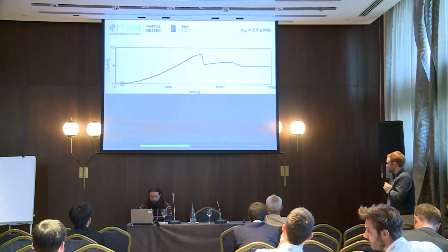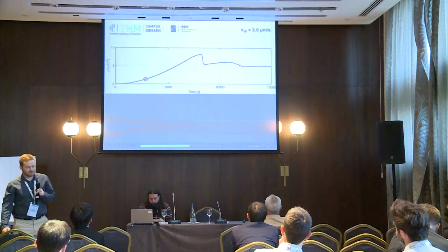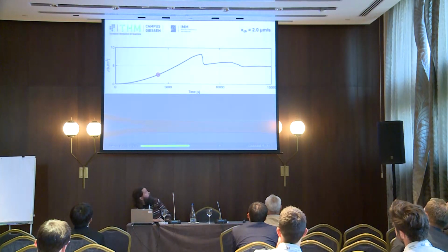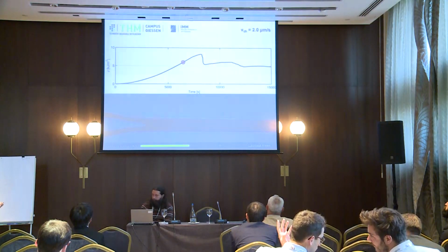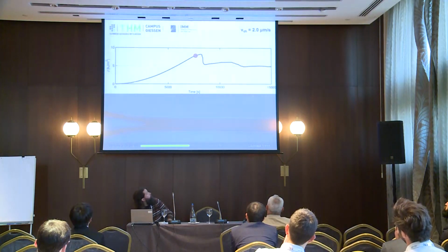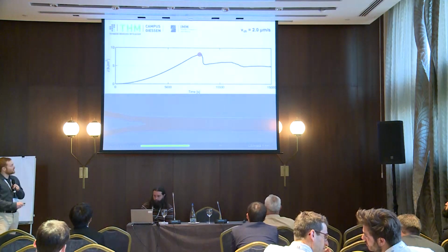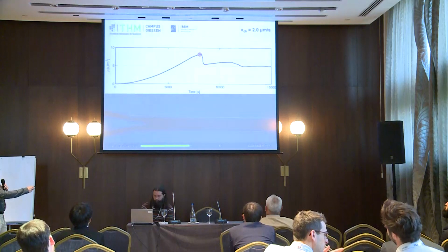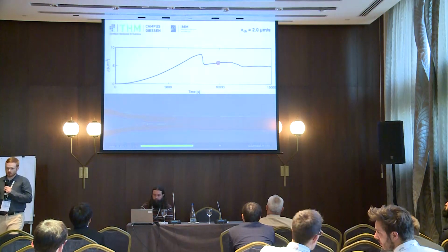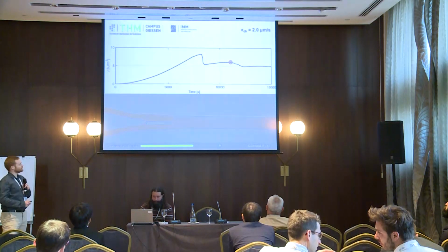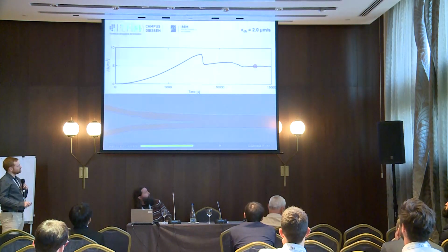We are looking now at videos which were made from the side. You see the lowest test speed, driven at 2 microns per second. You see a curve J over time. Crack tip gets visible now. And please look at the crack tip. Maybe you see it. We have subcritical crack growing before reaching maximum J. Now we reach the fracture energy and we have a crack jump. And after this crack jump, the crack propagates nearly stable anew. We have no sawtooth shape here.